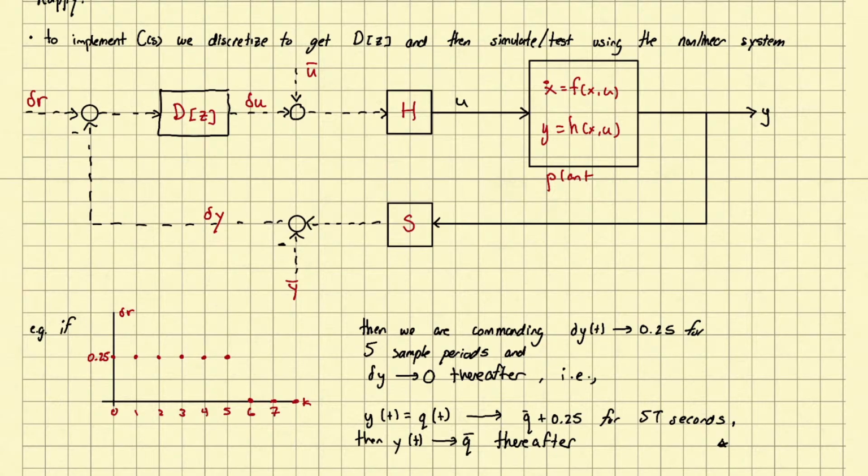You might get unpredictable behavior because your controller is based on a linearized model, and if you move too far away from the equilibrium, that model starts to break down. Okay, so control design using linearization, right? The key takeaway, the most important thing, is the last step, right? When you go to implement and test, how do you interpret what you've designed physically?